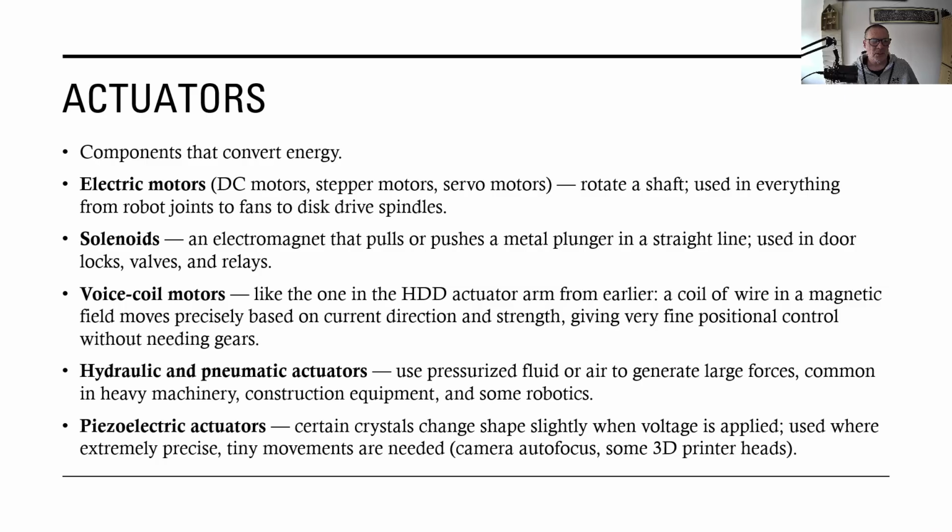Hydraulic and pneumatic actuators use pressurized fluid or air to generate large forces, so they are commonly used in heavy machinery, construction equipment, and some robotics. And piezoelectric actuators contain crystals that change shape slightly when voltage is applied. So this is used where you want precise small movements, for example, camera autofocus.